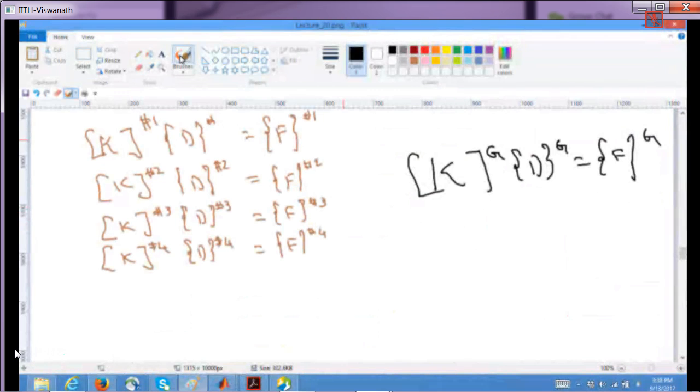I have done this part, I have done this part, and I have also considered elastic foundation or elastic spring. So I even considered the part of elastic foundation. So one constraint has already been added, but still this is not invertible. If you try to take the rank, you still see that it is rank deficient. Why? Because the structure, without putting a kinematic boundary condition, would not be stable.